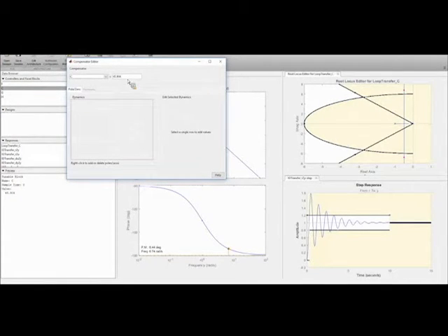And so here it shows that the way I manipulated that currently has a gain of 45. We're going to change that in a second. All right, and then you can right-click on Dynamics, add pole zeros, and you can do a lot of different things, in terms of adding real poles, real zeros, etc. But the shortcut one is you could actually compose this of individual poles and zeros if you want.